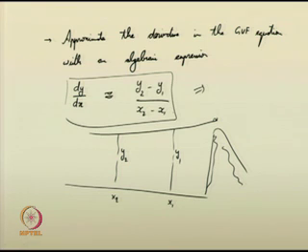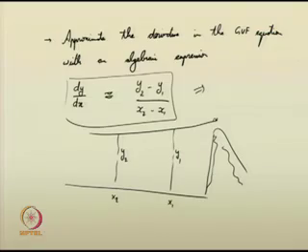So, such approximation is done. Then all other terms which involve quantities or functions related to depth can be averaged accordingly, and you can use them in the equation. Not only for a differential equation, if it is a partial differential equation, the partial derivatives are also substituted by algebraic terms, and the corresponding equation becomes an algebraic equation. So, that algebraic equation is solved. That is the objective here. The first method which we are going to do is the direct step method.